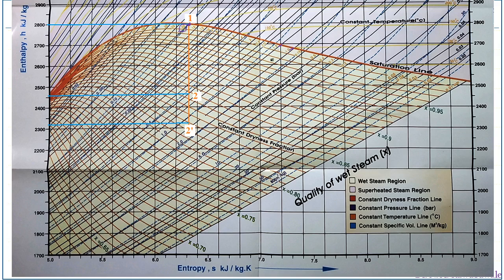So somewhere here in between there may be a curve. So we approximately assume that it is at the center of these two curves. So we assume this curve of pressure 1.2 bar is here. If we expand steam from 1 to 2 dash directly to the back pressure of 1.2 bar, this point 2 dash is located. Meanwhile, point 2 has to be located at a pressure of 3 bar. So here we can find the pressure of 3 bar. This line indicates the pressure of 3 bar. Wherever it intersects, this point is marked as point 2. Points 1, 2, and 2 dash we have marked on the Mollier chart.